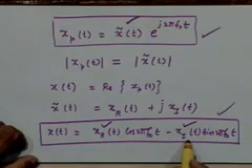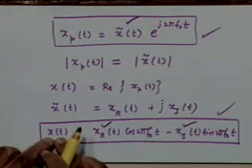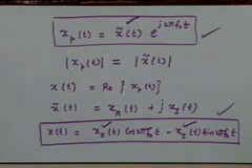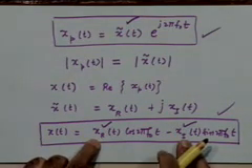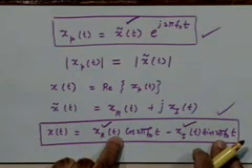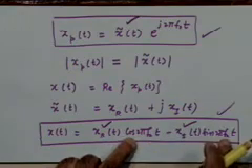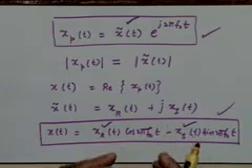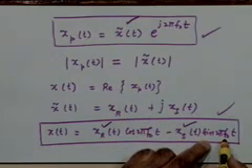So I can represent x(t), an arbitrary band pass signal, in terms of two low pass signals multiplied with quadrature components of a carrier. We call cosine 2 pi f naught t the in phase carrier and sine 2 pi f naught t the quadrature phase carrier.